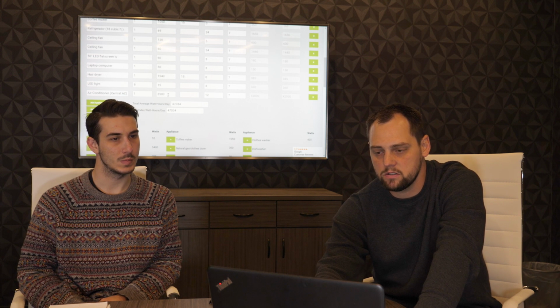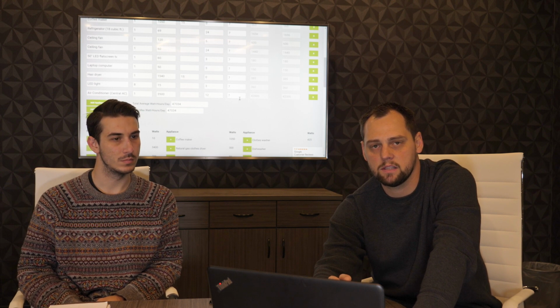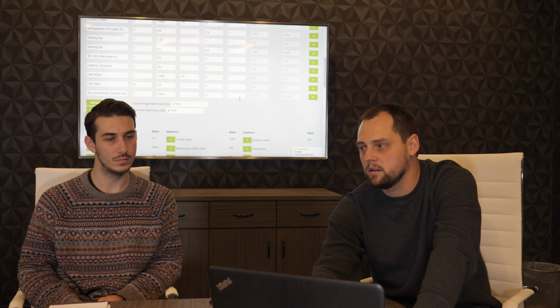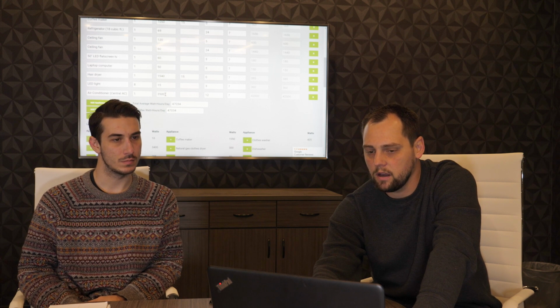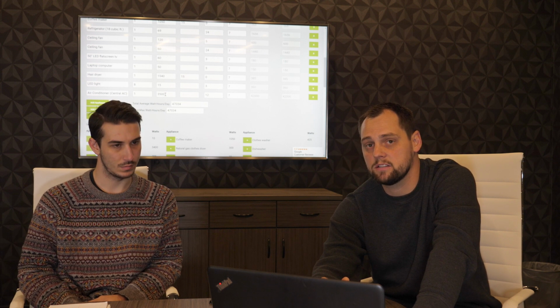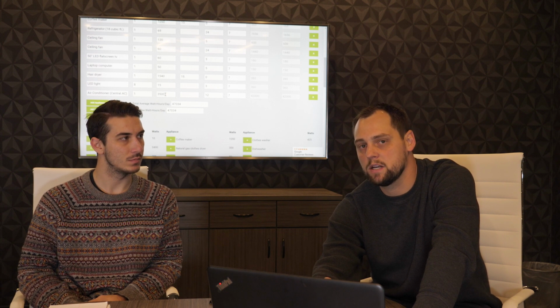This particular air conditioner is a standard unit, I think 2 to 3 tons, something like that. We find that a lot of people in off-grid applications tend to use mini splits or inverter-based heat pumps, and the amount of energy they use for a similar conversion is usually a lot less. So take a look at the actual appliance you're going to be using, and don't just use an estimated value. Find out what air conditioner you're going to use and input that information, specifically the model as well, into this line here.